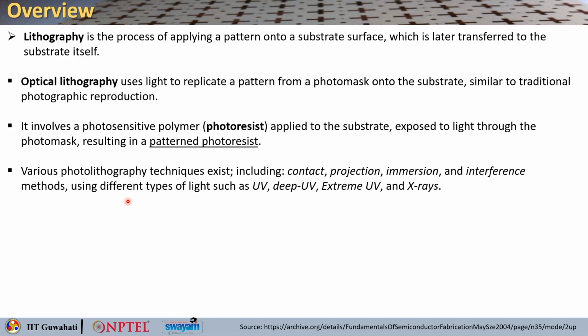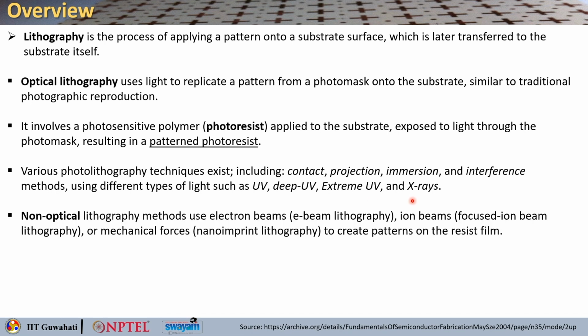Various photolithography techniques exist, including contact, projection, immersion and interference methods, which use different types of light such as UV, deep UV, extreme UV and X-rays. Different lights are used for different resolutions of the structure that you want to pattern. So, we will see that later.